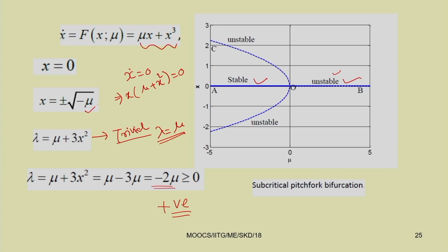Also the type of stability is changing. Here the resulting response is unstable; previously we had a stable branch and two unstable branches, and now this becomes completely unstable. This is known as subcritical pitchfork bifurcation, which is a dangerous bifurcation, because after this, as there is no solution available, the system response may jump to infinity and the system may tend to an unstable region, or